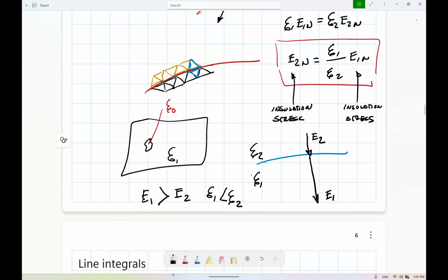Yeah. So how do you understand the stress? How do I understand what? The stress. The stress is electric field. Yeah, but how does the stress behave? Would the stress be maximum when two different materials contact each other? No, that will be minimum. The minimum is when epsilon 1 is equal to epsilon 2. When the permittivities are the same, that is when you get the minimum. When two different materials are touching each other, you're saying that's where the stress is coming from, right?